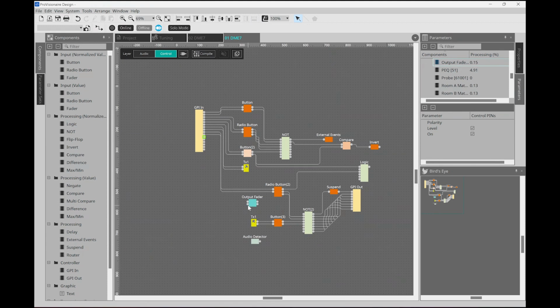In this mode, the fader selection button will mirror the state of the GPI, so if the pins are open, the button will be off, and if bridged, they will be on. If I wanted to reverse the above, I could use an invert function. So this will take whatever you put in and will send out the opposite.